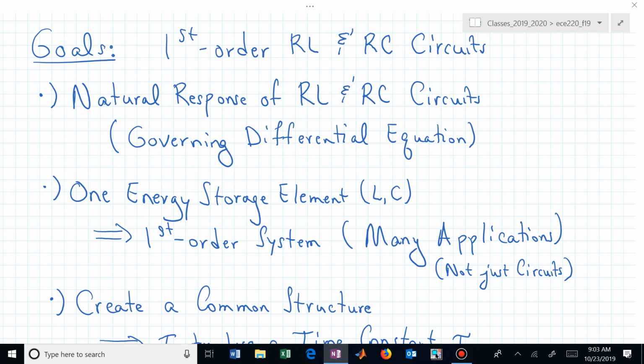Those could be equivalently made into one inductor. You might have a circuit that has 2 inductors and you go, I can't analyze this. I only know how to solve first order circuits. Well, look around. Hopefully they can combine. If they can't, then we're into second or higher order circuits, and you have an excuse for not knowing how to solve that just yet.